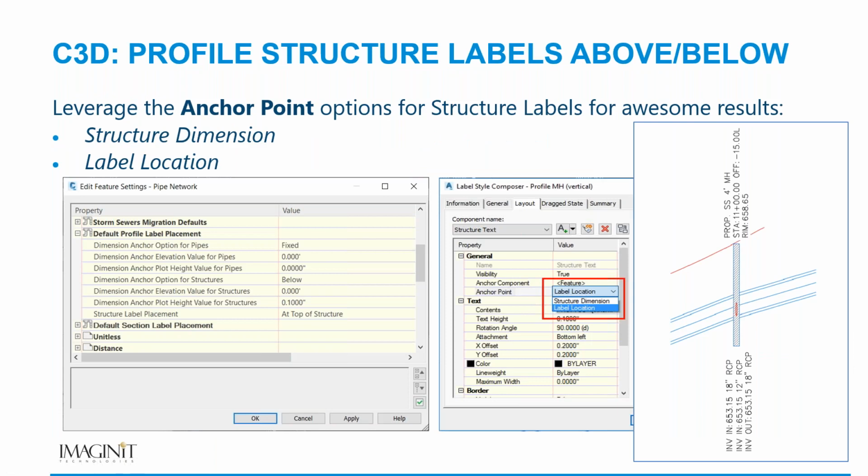And ultimately, talking about labels, you can create really wicked cool labels inside of the Civil software if you set them up appropriately. So you can have a manhole get information at the top and at the bottom. This is just an example of how I can get maybe the name of the manhole, the rim and station information, and invert information at the bottom. It does understand these pieces, but you need to make sure that you set up the software appropriately so we get these labels to work out for us.